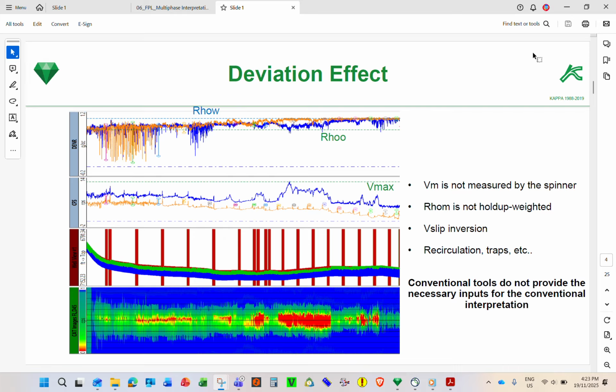In horizontal it's difficult to get because you cannot use the wireline. You cannot use just the slickline. You need to have it conveyed with other things like coiled tubing or the tractor. I mean it's supposed to have 6 spinners. So you have two passes maybe, two up passes or two down passes or one up, one down.